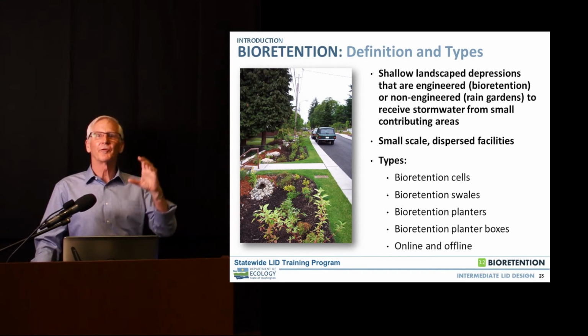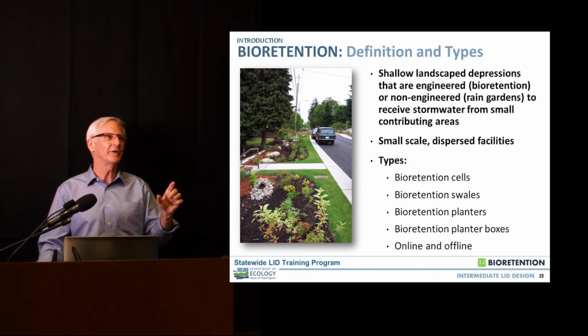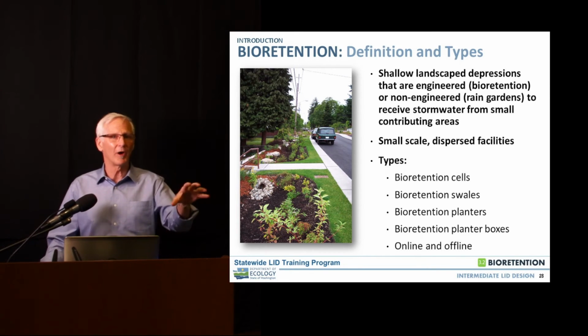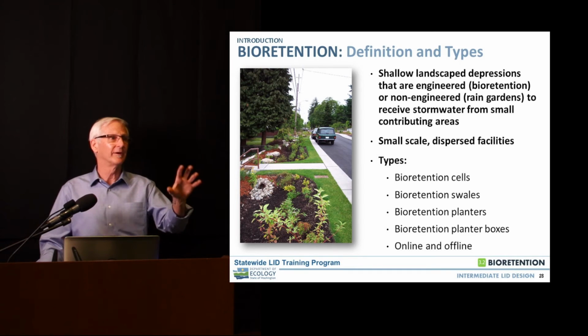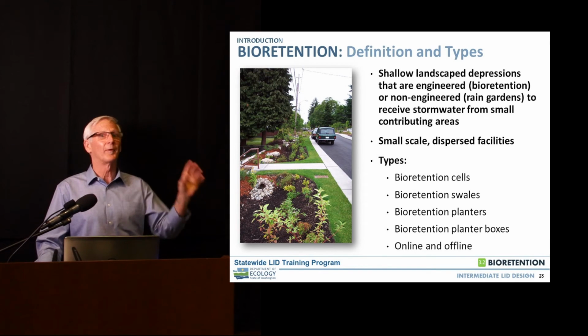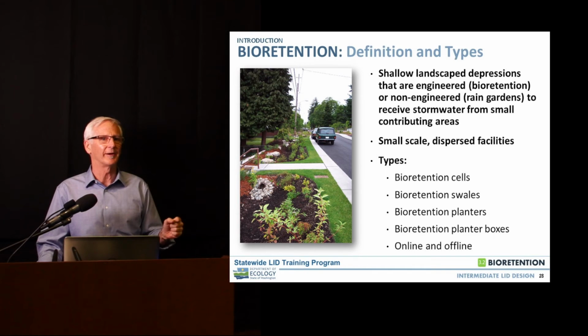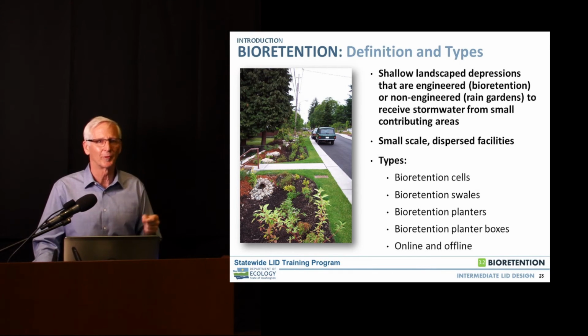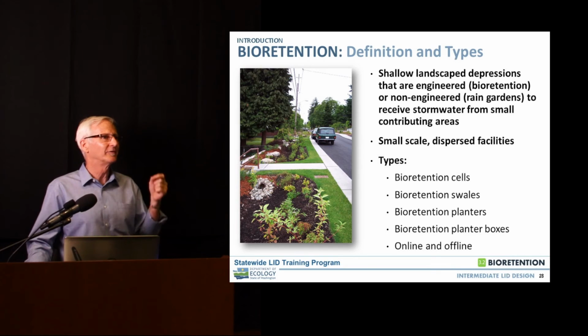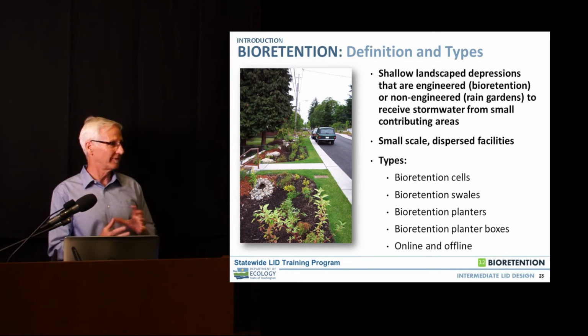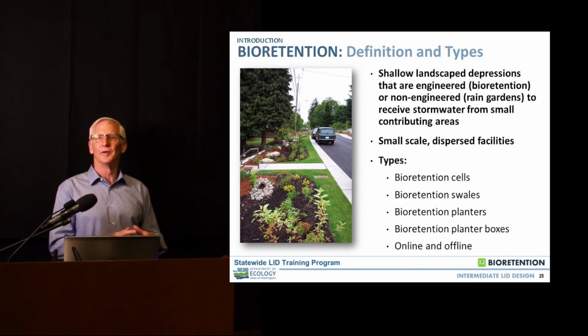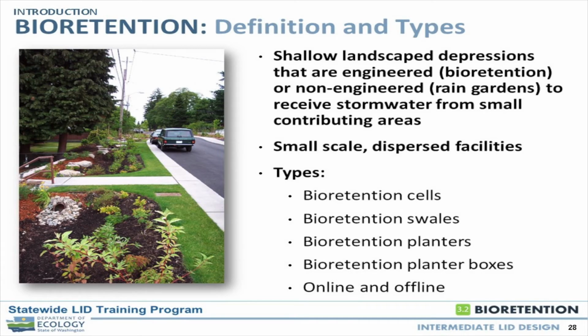There are thresholds as far as the contributing area to bioretention areas where you can use a smaller correction factor rather than a larger one, 2 rather than 4, if you're under certain thresholds for the contributing area. That's purposeful in the Stormwater Management Manual. We wrote that in to promote the use of this approach for small contributing areas. And there are very large advantages to designing with small contributing areas.